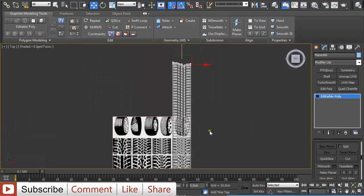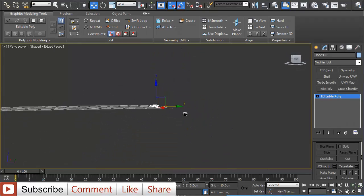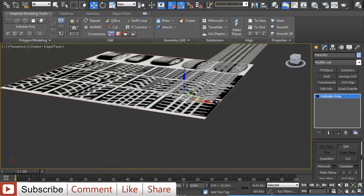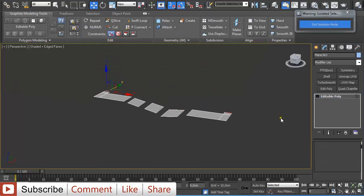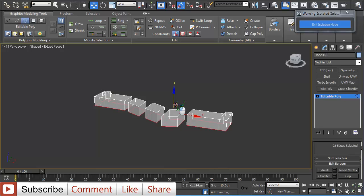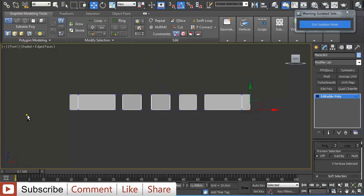Click OK, and then I'm going to create some depth on these instances. So I'm just going to select one, Alt Q to isolate it, 3 on the keyboard, select all the border, and then holding shift I just drag it down a little bit. In the front view I'm going to select these vertices, pressing R, and move them outwards,